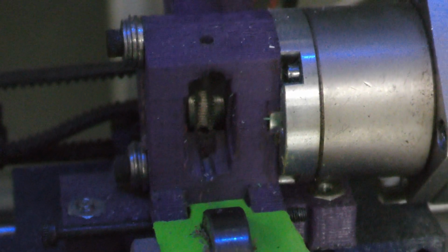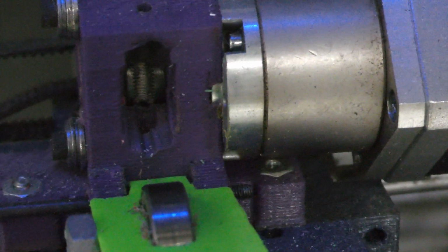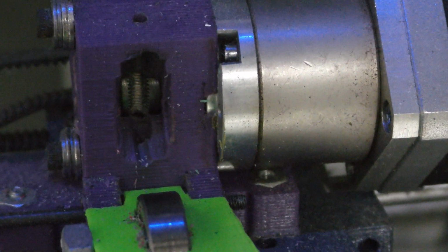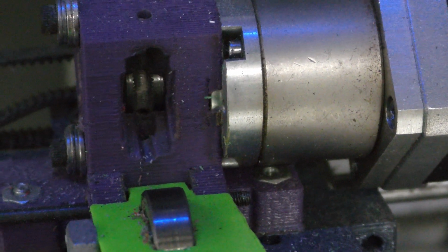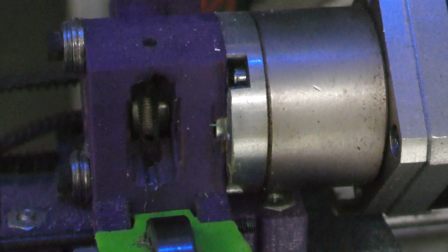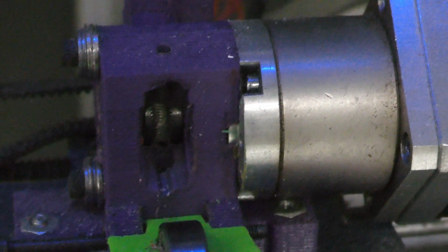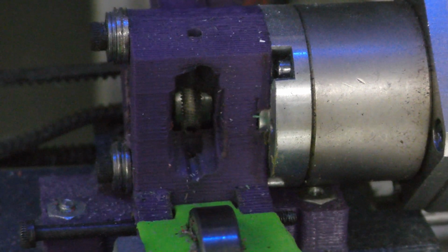That's how you remove filament. And what I'm looking at is in here, there's a little wheel. See the little wheel? I'm going to hit extrude on my phone, and see how it moves. Okay? You notice how dirty that wheel is. It's pretty bad. So that needs to be cleaned.